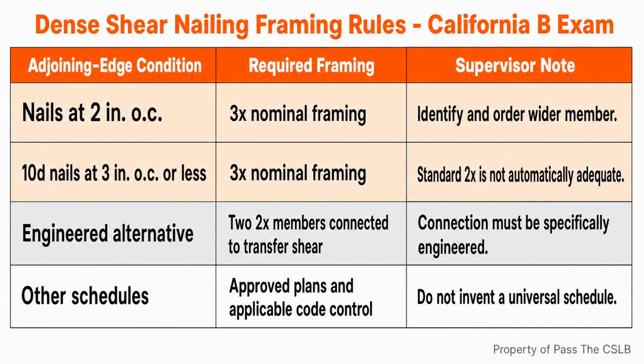The second defect is an overdriven nail. This happens when the nail head is driven below the intended panel surface and crushes through the outer veneer or face material. The nail may have hit the framing, but the head has damaged the material that distributes force into the panel. The deeper the head is buried, the less effective panel thickness remains under that bearing area.